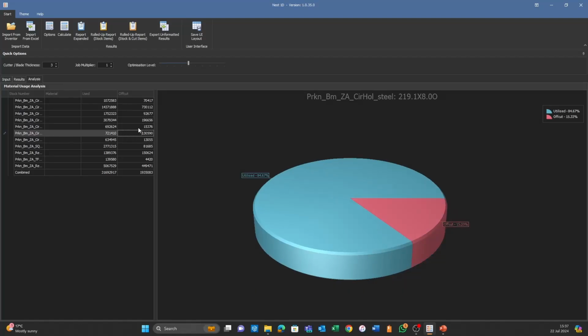And you can see that utilization actually differs between different elements. So with this particular one, I think that is actually quite good. The utilization is 96.93, and then the offcuts are only 4 meters. So sometimes these amounts would be unavoidable, but you can see those are actually quite excessive, and you can go back to your project and try and address them.